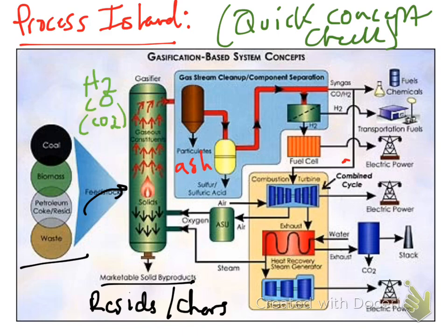After the syngas leaves the gasifier, it has to go through gas cleanup. Particulates are removed, ash. You have sulfuric acid treatment. Usually that's to pull out the sulfur.